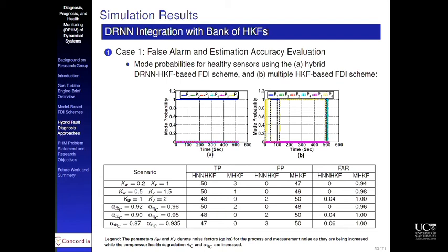This is a solution that you get without the neural network put into the system. This is a solution in the first part that I just mentioned. So you see, even when the system is healthy, and even this method that I claim to be so good, with this simple modification of onboard engine model gives me a lot of false alarms. So this is even not good enough. Whereas with adding this neural network, we get a very clean kind of a classification.